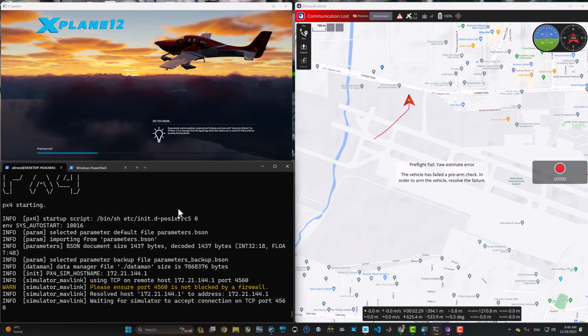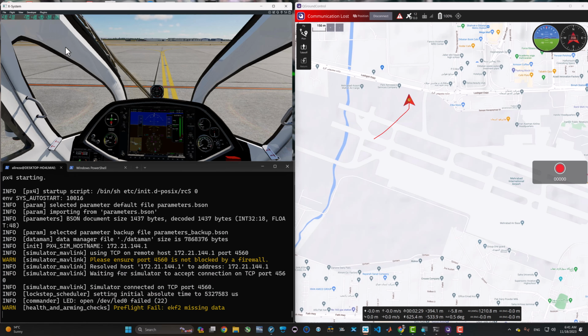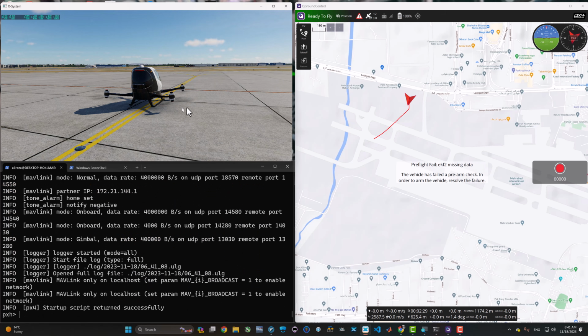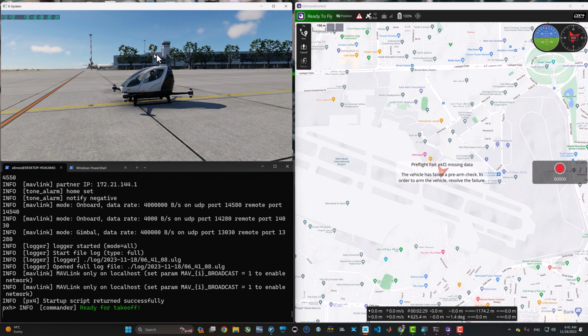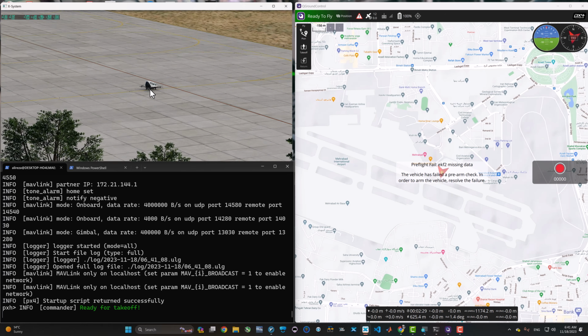Here we are. We just again run PX4 software in the loop non_iris. Again from plugin menus, we hit select connect to SITL. QGC regains the connection and updates our position. And software in the loop also is mentioning that we are ready for takeoff. This time we are not gonna do manual flying. Let's do a plan mission. This is our view from the Merhaba Tower.